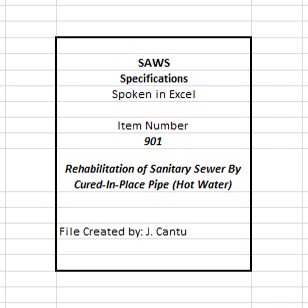3. Structural requirements. A. The CIPP shall be designed as per ASTM F1216, Appendix X1. The CIPP design shall assume no bonding to the original pipe wall. B. The contractor must have performed long-term testing for flexural creep of the CIPP pipe material installed by his company. Such testing results are to be used to determine the long-term, time-dependent flexural modulus to be utilized in the product design. This is a performance test of the materials, tube and resin, and general workmanship of the installation and curing.